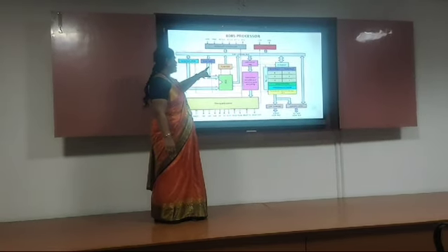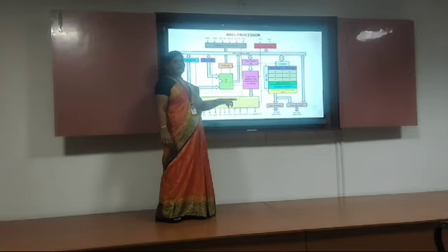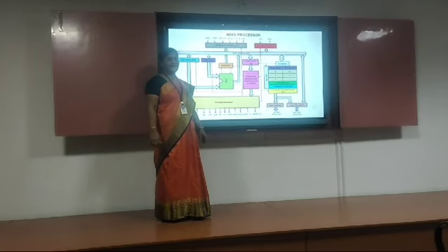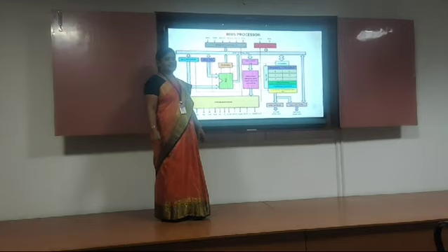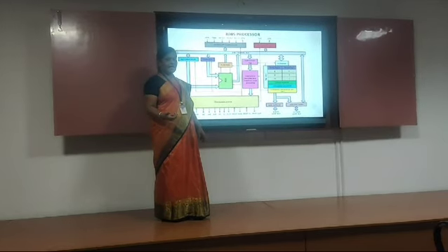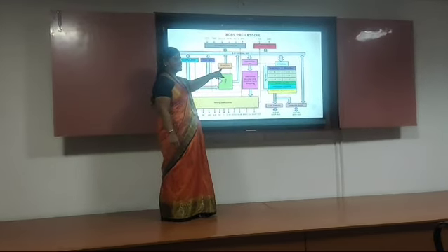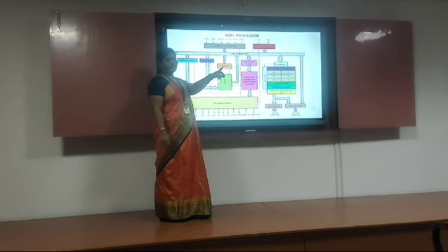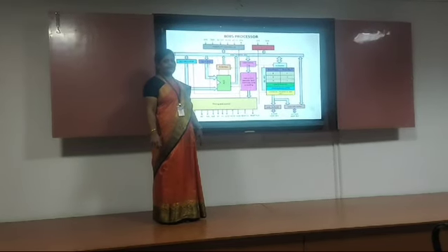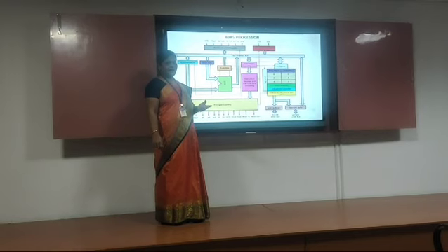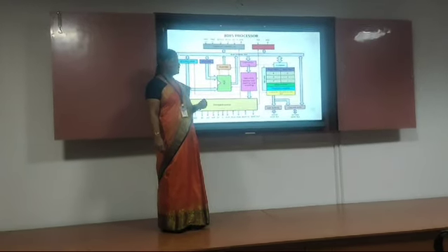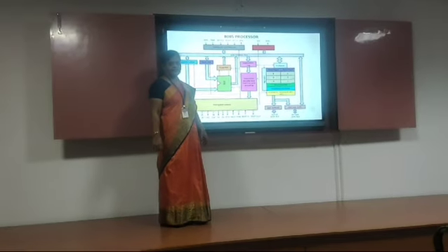Next we have various registers, flag registers. The purpose of the flag register is that it will just indicate the status of the result, whether we have any carry or zero or like that. Everything is indicated in the flag register. Totally we have 5 flags in 8085: sign flag, zero flag, parity, auxiliary carry and carry flag. So these are the 5 flags and the flag register is an 8-bit register.